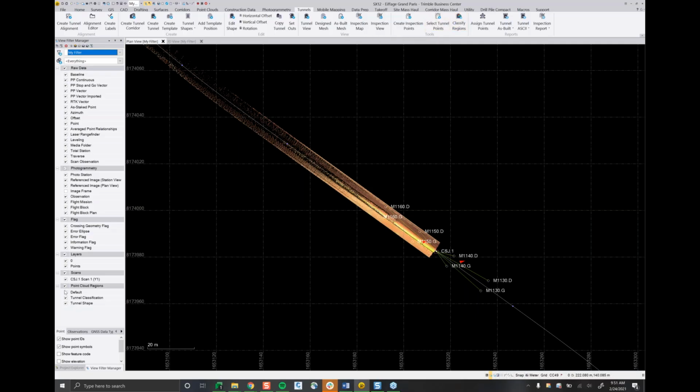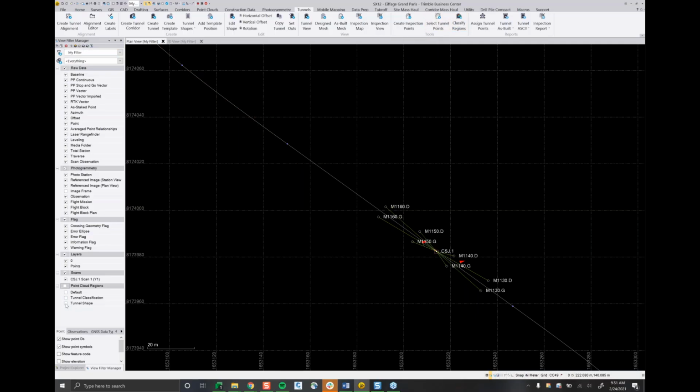And what I've done is I've created a region, cutting off all the excess data, the tunnel data that didn't get shot in with that SX12 scan, just to help the algorithm out in finding all of this. Ideally, you would have an SX12 go through the entire tunnel, so you have a swath of survey data or point cloud data that really helps guide that algorithm.